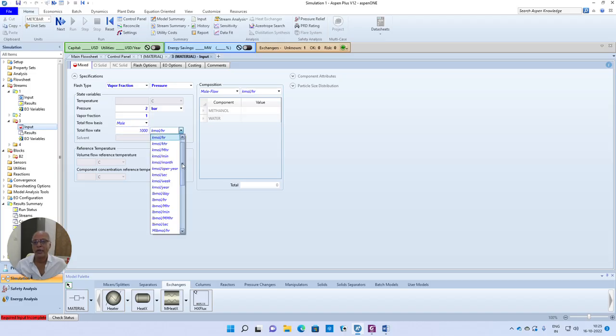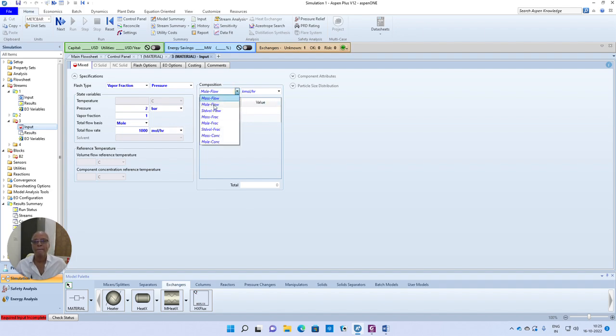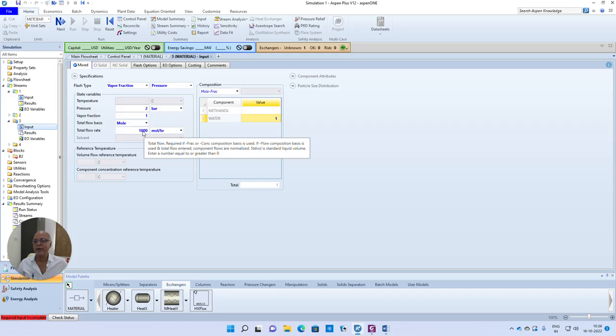I hope the necessary heat duty will be met from this stream. Otherwise, we can revise. So this is mole fraction or mass fraction, pure water. So the utility fluid has been assumed to be saturated steam at a pressure of 2 bar with this flow rate, right? Pure component. Now that should take care of stream 3.